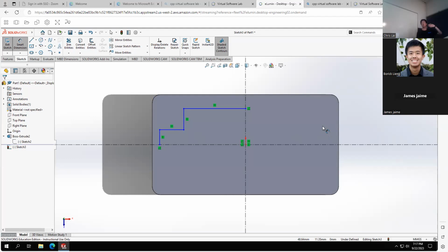So for those of you who have used SolidWorks, this is actually a pretty neat trick that I learned. When I go into my smart dimension, for example, I'm going to want my sketch to be, let's say, 100 millimeters from right here to right here. So when you're making a sketch, just part of it before you start mirroring everything, you don't have to think in quarters or halves, like, how much is this going to be? Maybe from here to here is like 50.